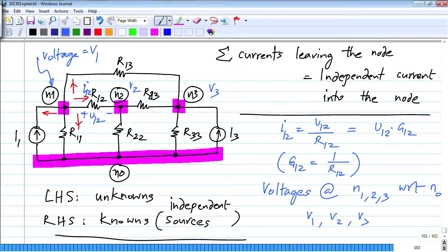So that's about the conventions. To summarize, in this method, which is called nodal analysis, I will start with KCL equations at n-1 nodes. I will choose some node and call that the reference node. I will not write KCL there. I will write KCL at the remaining nodes. And what is KCL? It is the sum of currents flowing out of the node equal to 0.